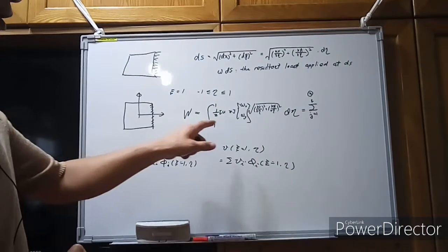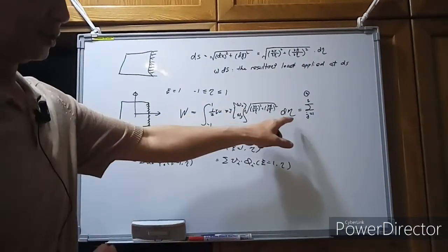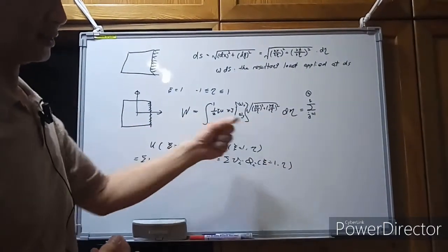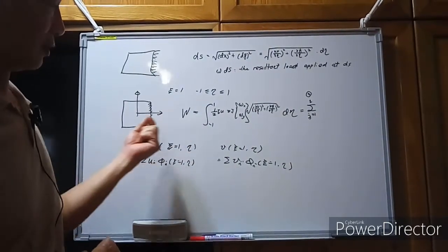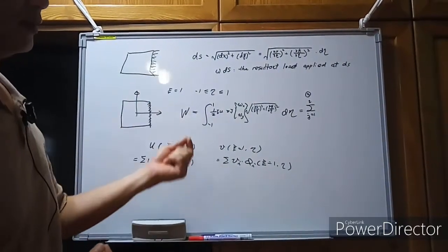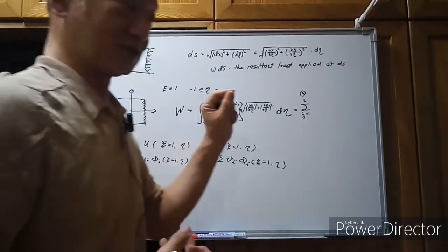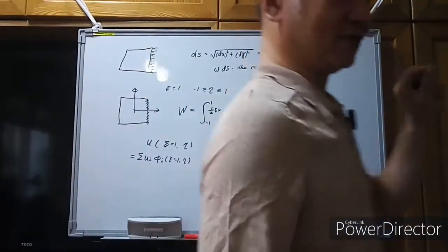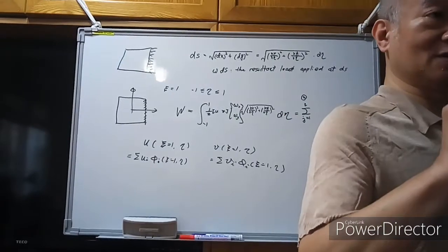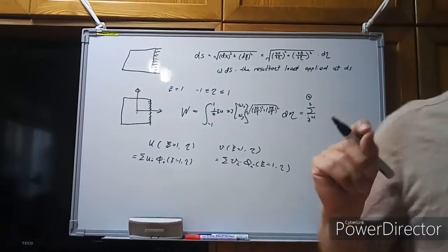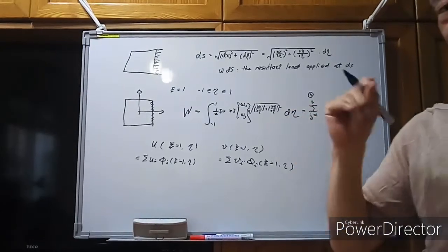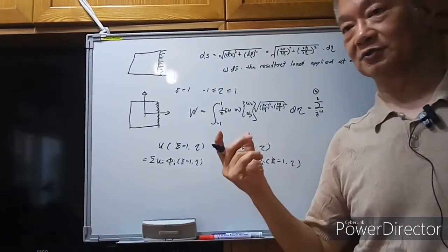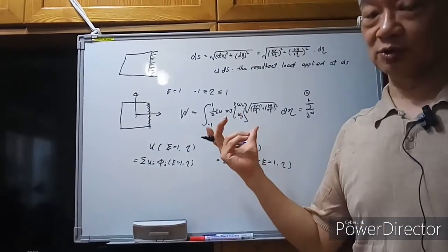So although it is an integration, the eta is changed continuously from -1 to +1. Also, we need to consider the eta in an infinitely small d eta. But in the numerical integrations, we just calculate the function values at the integration points.